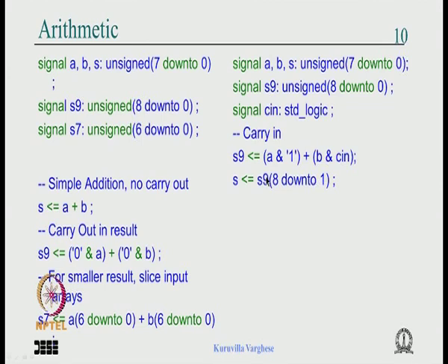And in some cases you want a carry input which is required, say you are forming a 2's complement number, so you have to invert some number and add 1 to it to get a 2's complement number for signed arithmetic. That can be achieved like this.